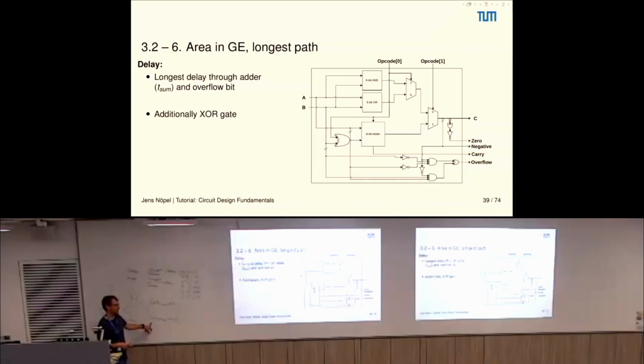And you have no idea how they compare in that technology. But what you then do is divide it by the delay of the NAND gate in that technology. So this is the delay of the NAND gate of vendor A. And then you get a rough feeling of how fast the 3-input OR actually is in that technology, right?